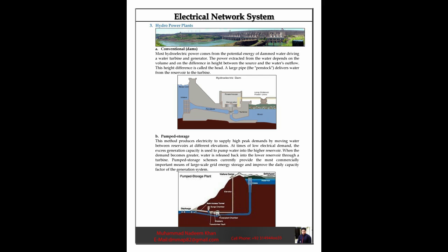When the demand becomes greater, water is released back into the lower reservoir through a turbine. Pumped storage schemes currently provide the most commercially important means of large-scale grid energy storage and improve the daily capacity factor of the generation system.